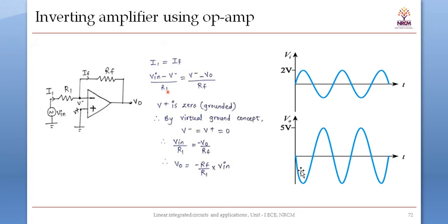If I go for another factor also, you can achieve the amplification, but you cannot achieve amplification more than the battery supply voltage. It is a rule of physics that you cannot achieve amplification more than the DC supply voltages. If 15 volts are applied, the maximum output will be 0.9 times your VCC, that is, approximately 13 volt will be the maximum output provided by the amplifier. So this is about your inverting amplifier.